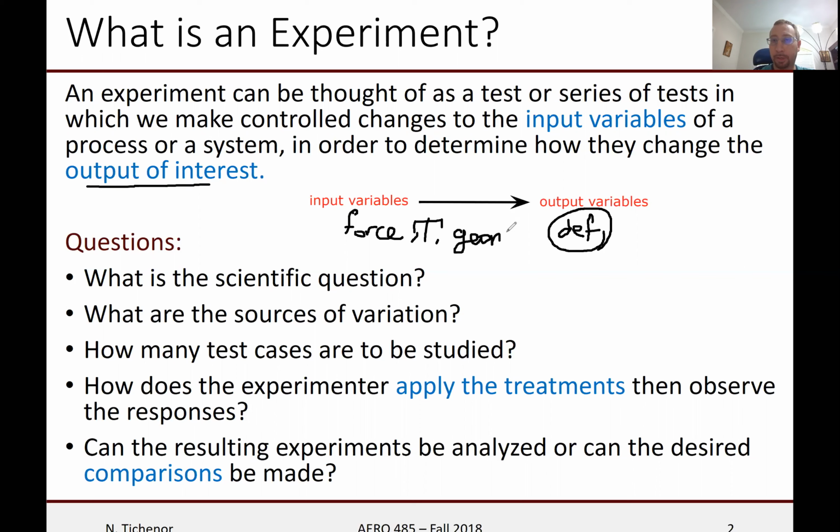So the question is, in designing the experiment, we first want to identify the real question, which in this case is how deformation is related to force. We want to identify all the sources of the deformations, which in this case is not only force, it's also temperature and the geometry of the sample. We want to see under what conditions we need to run the tests so that with minimal costs, we can identify this relationship.